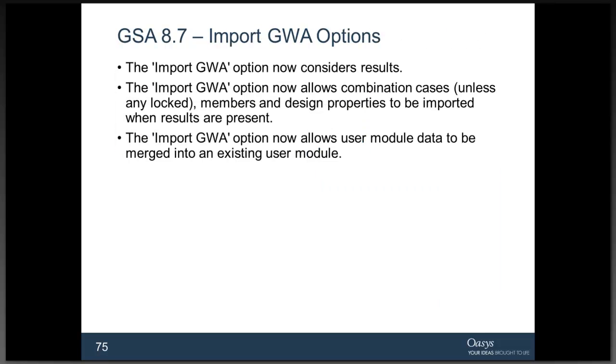Import GWA options. There are quite a few enhancements to this feature. You can import results via GWA, and combination cases, members, and design properties can be imported even when the results are present. And you can import user module data into an existing user module.